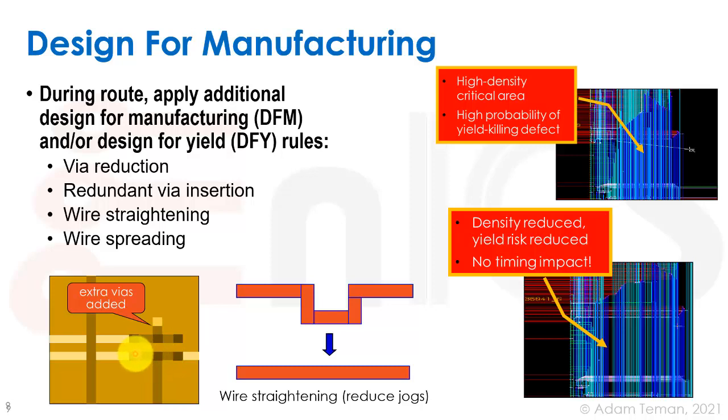Same if we have an electromigration problem and one of them blows out, we'll still have other ones to take its place. And second of all, it reduces the overall resistance and current density for electromigration problems that we'll have through these vias. So really, if we can, we want to put as many vias as possible across the design. In many of the rules, you'll go over your design and see how many single vias there are versus double vias, and you'll want to have a very high percentage. It could be even 90 or 95%. You want to have double vias across your router design.